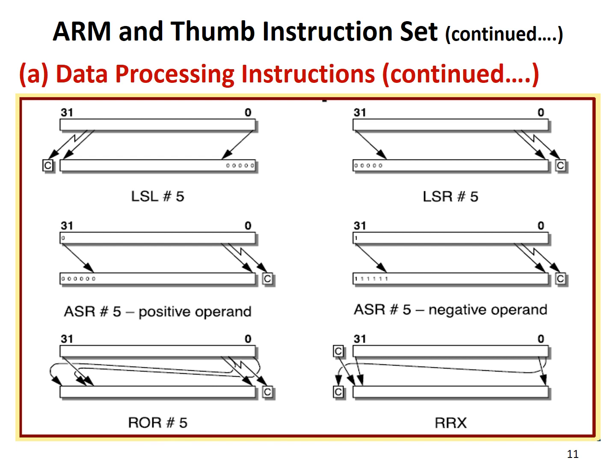This is the difference between the arithmetic shift and the logical shift. If logical shift left by hash 5 is mentioned, it will shift the bits towards the left by 5 bit positions and the empty space is filled with 0. Similarly, for logical shift right, it will shift towards the right by 5 bits and the empty space is filled with 0. But in the case of arithmetic shift right, for 5 bits it will shift towards the right, but the empty positions will be filled with the MSB, whether 0 or 1, in all the empty fields.